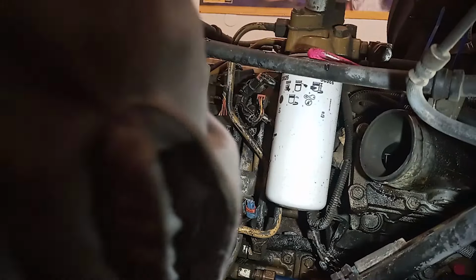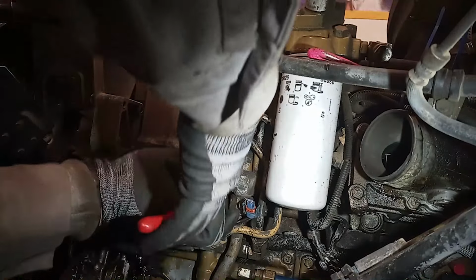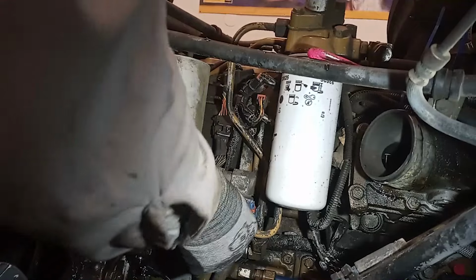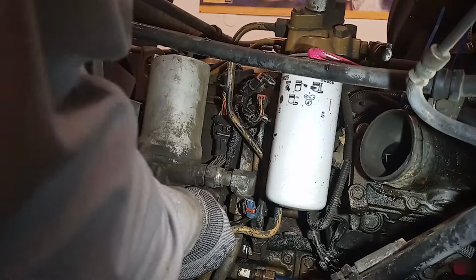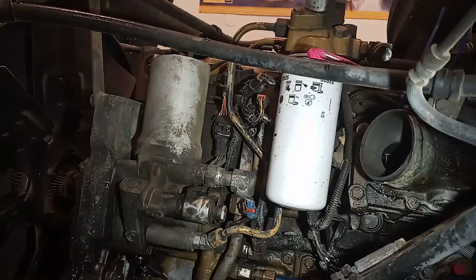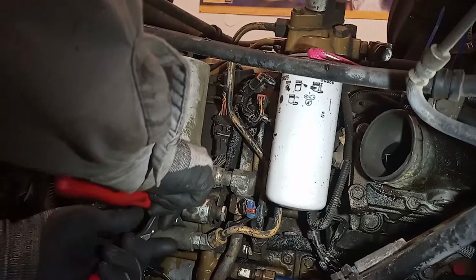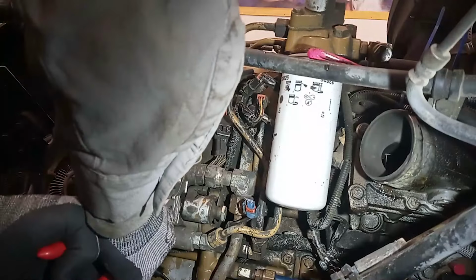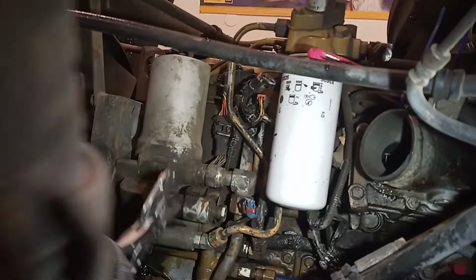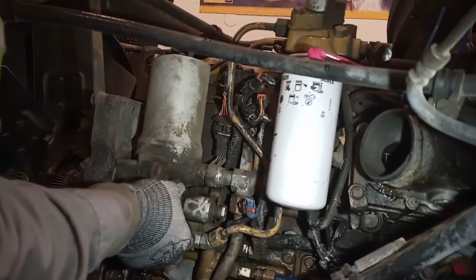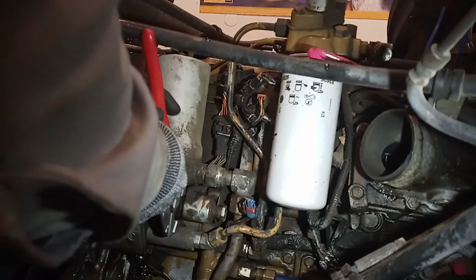Now, if you're loosening really tight bolts, I don't recommend it, but I like using it on something like this because you can get a better grip on such a thin fastener as these little retaining nuts are, especially between the solenoid and the pump housing. It's not super tight, but this thing will get a really good grip on it, and it'll break it loose without stripping it out. It also has thinner jaws than a wrench, so you're not getting better leverage, but you'll have a less hard time getting a big old wrench in there than you would with this little tool.